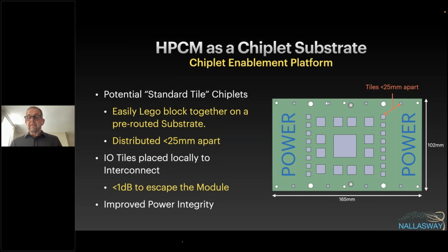Yeah, so there is one technical issue that is more based on the current state of the art. That is, the organic packages typically today are yielding in the range of, say, 80 by 80 millimeters. That's why you see those sockets. They are in that range. Yielding organic at 102 by 165, haven't seen anything. We've definitely seen packages in 100 by 100, but that doesn't mean that there wouldn't be a technology. I'm sure there will be some technology that can support it.